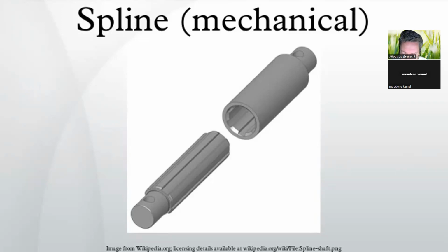Uses. Drive shafts on vehicles and power takeoffs use splines to transmit torque and rotation and allow for changes in length. Splines are used in several places on bicycles. The crank-arm to BB shaft interfaces that are splined include ISIS Drive, Truvativ GXP and Howitzer, Shimano's Octalink and many others, most of which are proprietary.